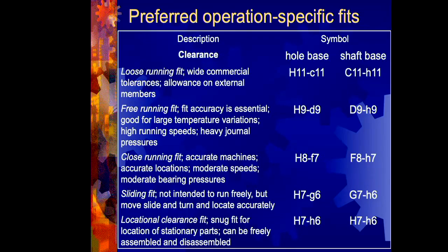On the left-hand column, for a series of different clearance opportunities, we've got loose running fit, free running fit, close running fit, sliding fit, locational clearance fit. What does that even mean? Well, there's some more words to help with the kind of fit you or we, the engineer, might be looking for. And nicely, we've got both hole and shaft base fit opportunities. And note, lots of capital H's and lots of lowercase h's.